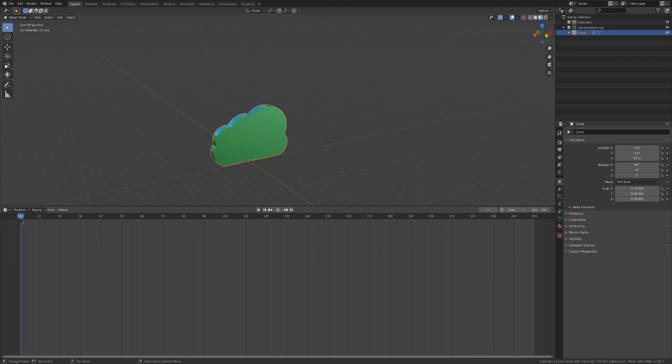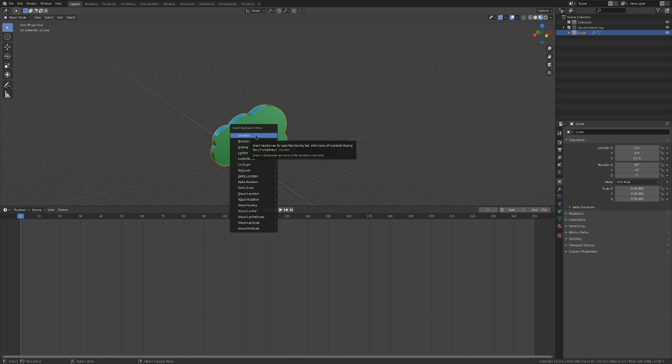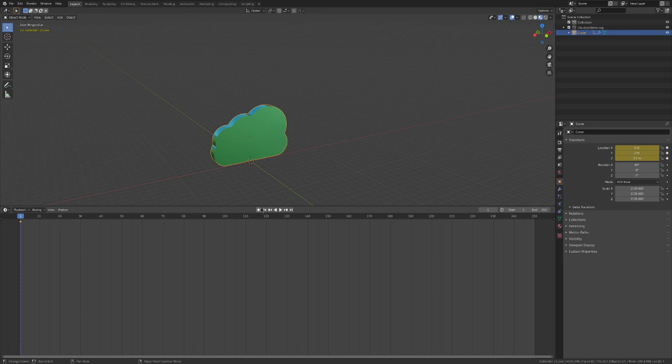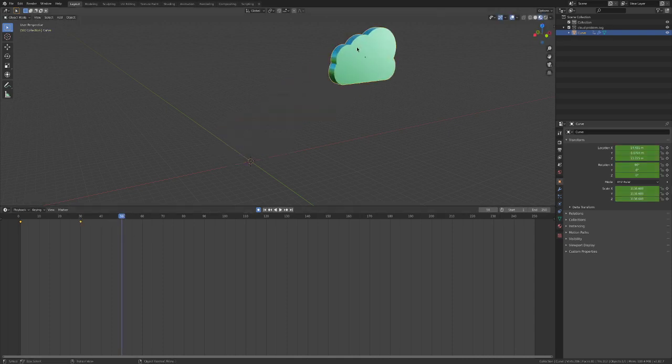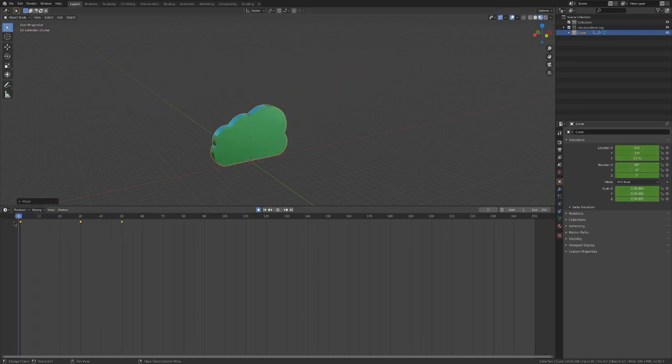And it's not inserting any keyframe. Let's add a keyframe for location, for example. Then I press this, then I move here, and then I move this here, and then I move here. So of course it's gonna work. But then if you don't have anything inside and you want to start adding rotation here, it's not really doing what I want. I want this to start normally. So I need to add the keyframe manually. Here it needs to be.